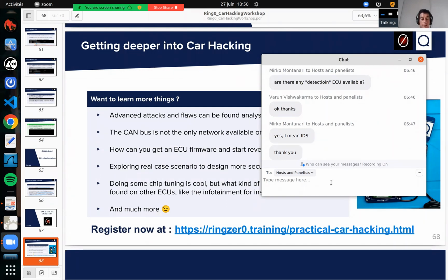On a car, each ECU is an embedded device, and on each ECU you will have maybe one or many firmware: a microcontroller, or one and a SoC, or not. So getting access to all the firmware and reversing them is very time consuming, because they are almost all different. If you have, for example, a Microchip microcontroller on one ECU, that doesn't mean that all the microcontrollers in your car will be Microchip. We will have NXP, we will have Renesas, and many others. And sadly, ARM microcontrollers are not the most common ones you will find in a car. Yeah, that's sad.